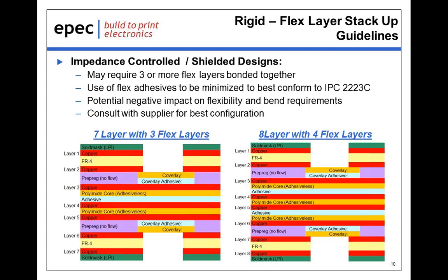Bonding the layers together, specifically when you get up into the 4 or 5 layer count range, does have a potential negative impact on the flexibility and the bend requirements, and that is something that should be investigated and understood completely as early on as possible in the design process. We strongly suggest that you consult with your supplier for the best possible configuration for these types of applications.